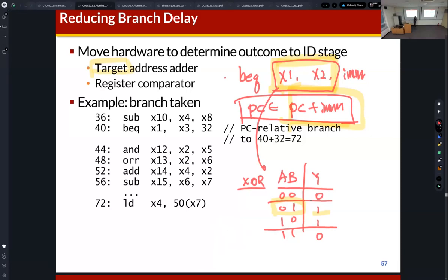So what I want to say is that the equality check is implemented using simpler hardware. And if we use simpler hardware, then the delay is also short. So we can include this delay in the clock period. Even though this short delay is included, we can make the sum of the delay less than the clock period. Okay.